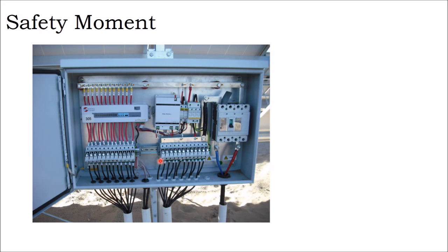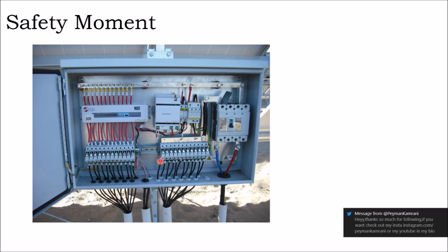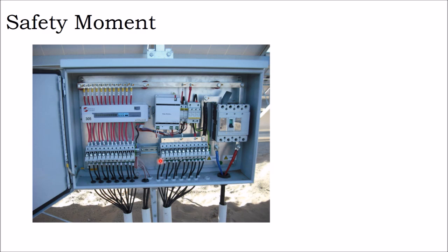Well, the problem is now the array is already faulting into ground. And so when the array turns on in the morning, the ground voltage rises along with the solar array. So all of a sudden you have an undetectable ground fault of ever increasing amperage and set the building on fire.